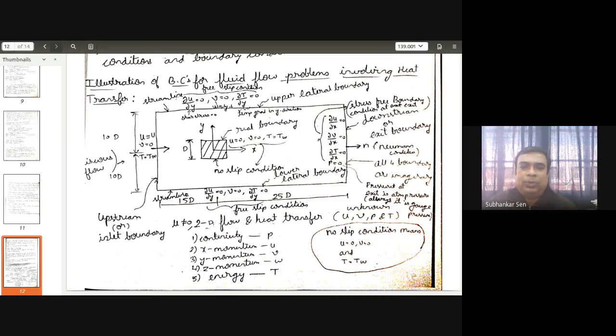If you want to do it using CFD, what do we have to do? Suppose air is filling the entire zone, but we have to specify that I want to solve the problem within this boundary. If the width of the building is d, I shall take maybe 20d or maybe 50d or 60d. So I shall take this much dimension within this rectangular domain to use CFD and solve. This need not be a rectangle, it can be a square or even a circular boundary. So in this particular problem, there are two boundaries: this is the internal boundary and this is the external boundary, and this portion is filled with the fluid.